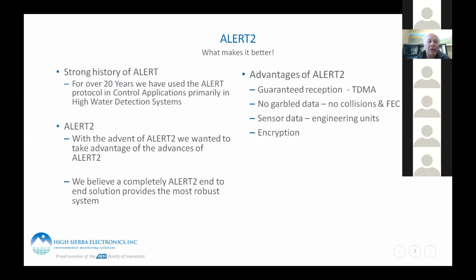collision. What we found in that case is the masters and remotes are generally pretty close to each other, and the signal strength is much greater than any collision coming in. So we didn't typically experience issues with the local system activating. But if you're going through a repeater, transmitting to a distant base station, in these cases, if you have collision, even though the local system is activated and behaving as expected, data collisions coming into the base station might be giving incorrect information.